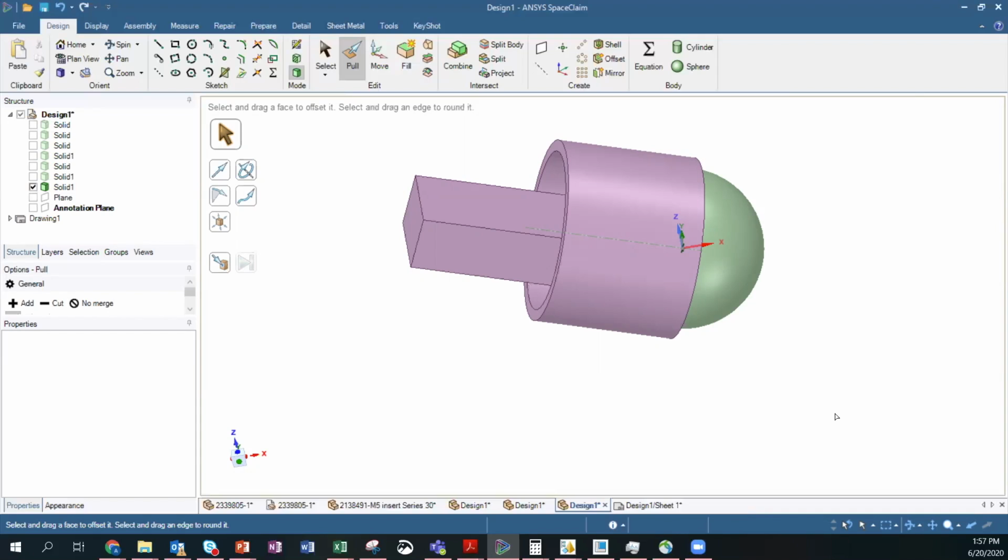But outside, if a lot of moisture comes and it's very hot, nylon is better. So that's how we make a choice. Or there are some grades of PBT that function better in humidity and water exposure. So we make the design and then we see the environment, manufacturability, and cost, then we choose the material based on it.